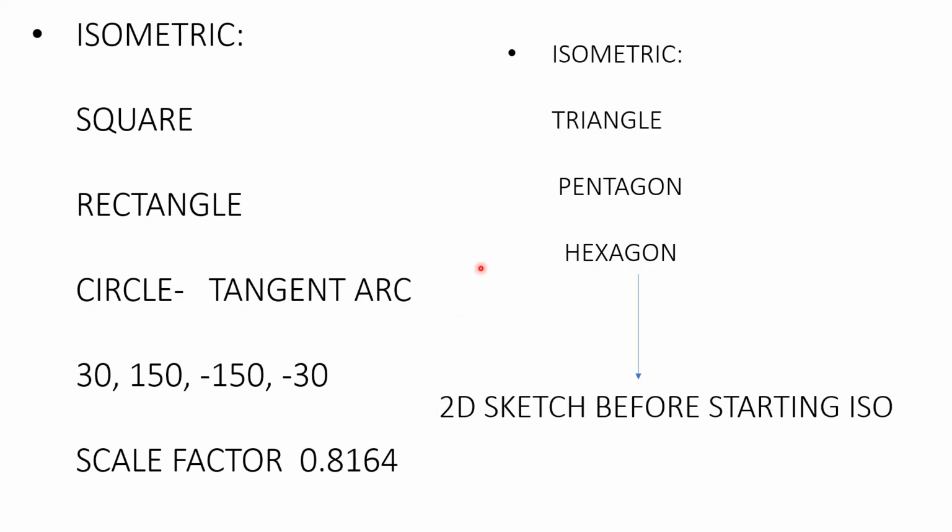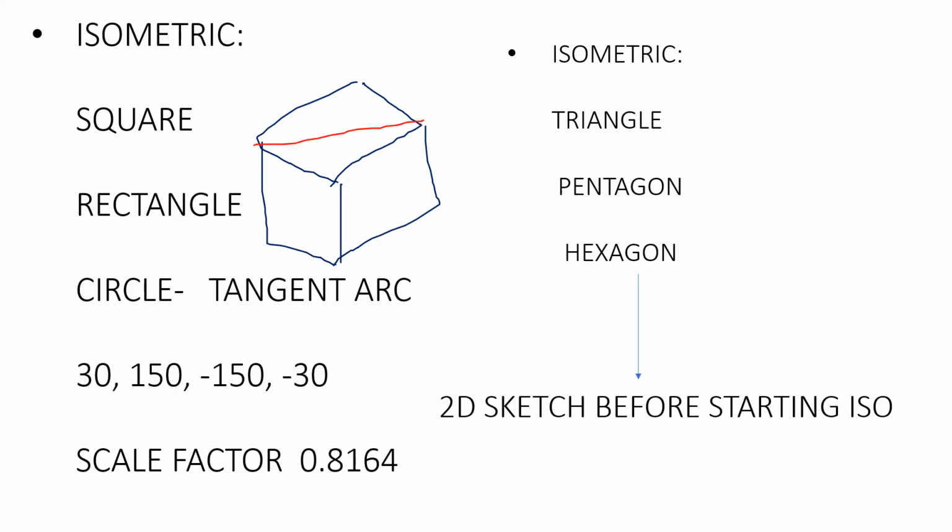For a hemisphere, again same, say for example, if there is a square block like this, we are going to have one cube like this. Then next thing is, locate the center of this cube line, and from there have the radius. Say this is the radius. Now convert this to the scale. Then once you convert to the scale, come back and take this as a center, then draw the circle. Very important. Just observe here. Many times you get told, this line is not going to touch that circle. So that's how exactly we're going to draw the sphere.